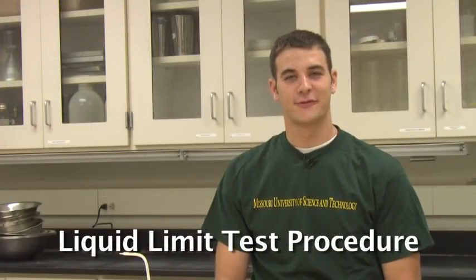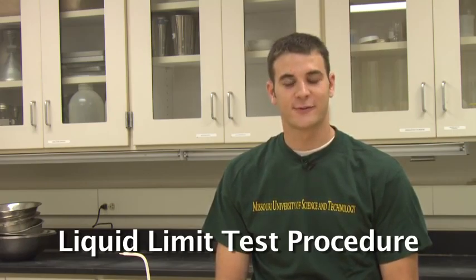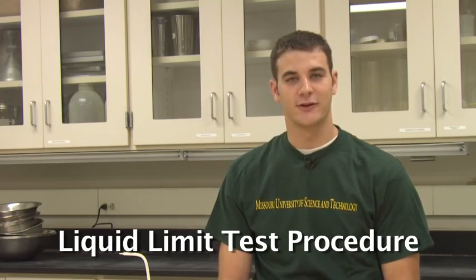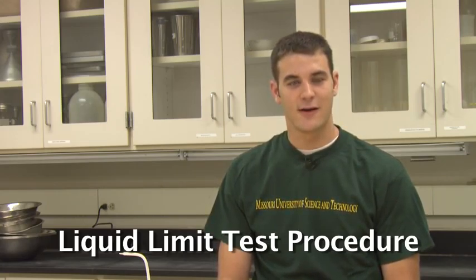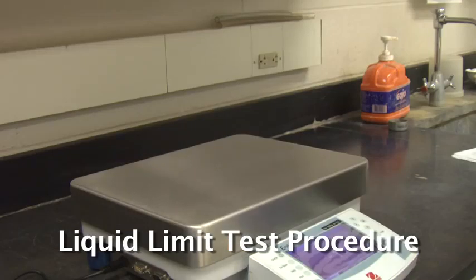In order to produce the flow curve, 4 liquid limit tests must be conducted. 1 test between the blow counts of 15 and 20, another between the blow counts of 20 and 25, a third between the blow counts of 25 and 30, and finally 1 between 30 and 35. As the soil dries out, the moisture content is reduced. This results in stiffer soil.